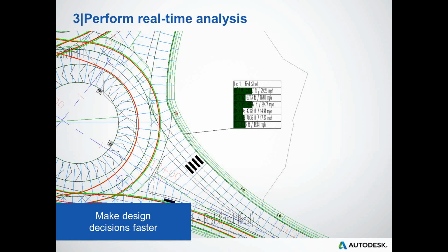Okay, so a couple of other additional analysis tools we have. You can visualize, if you want, sight lines for vehicles. That means sight lines: what is the driver of the vehicle seeing? It's not doing real clash detection at the moment. It's not saying you have a problem in this situation. No, it shows you the sight lines, and then it's up to you to decide that that big building is blocking most of the sight lines, so maybe it's not a safe situation.